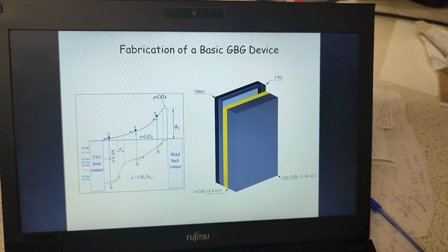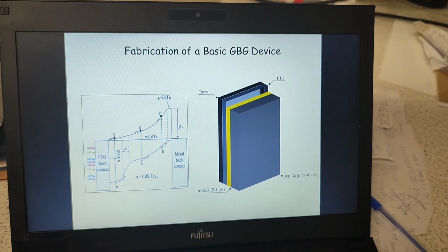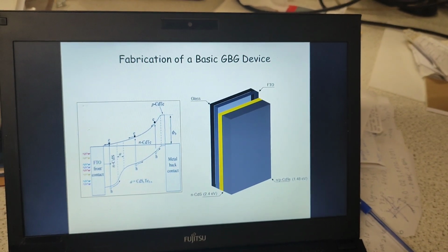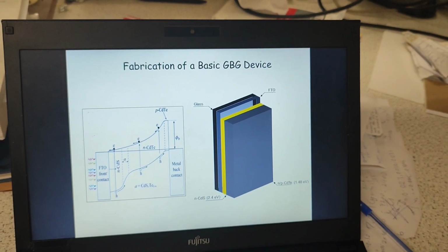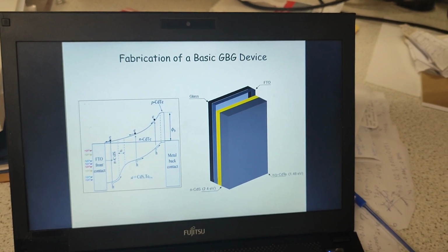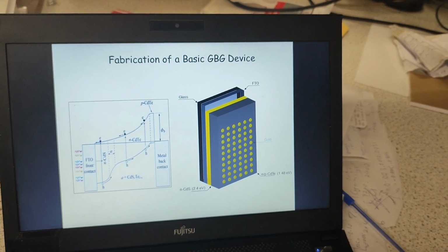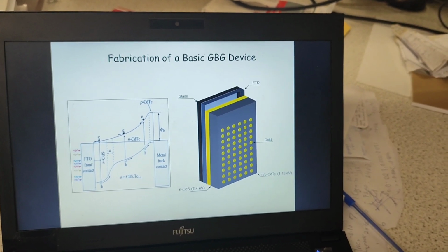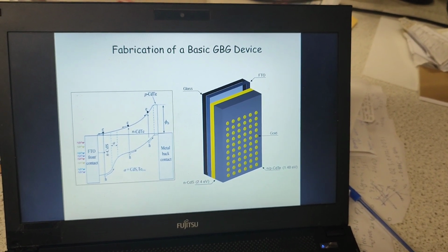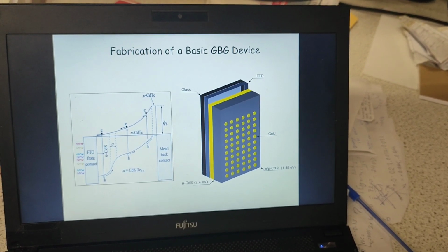That means we deposit our semiconductor layers. It can be an N-type semiconductor, and on top of that there can be an N+ semiconductor or a P-type semiconductor. After the last semiconductor layer is deposited, we deposit the metal contact, which can be gold, silver, aluminium, indium, anything. For example, in this animation we have shown the gold contact.